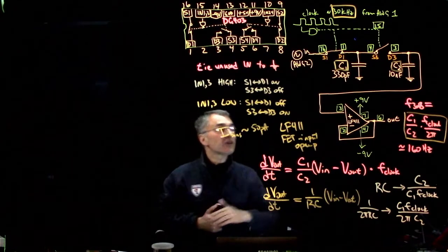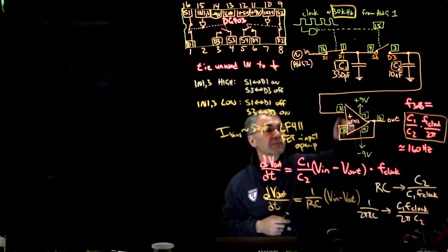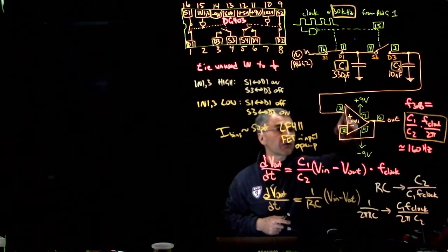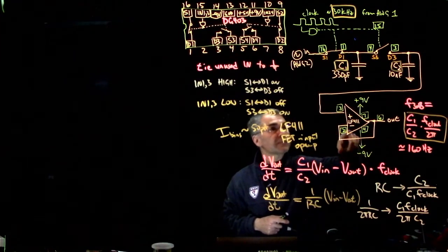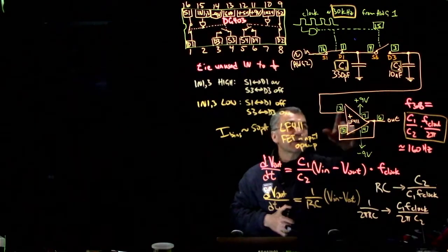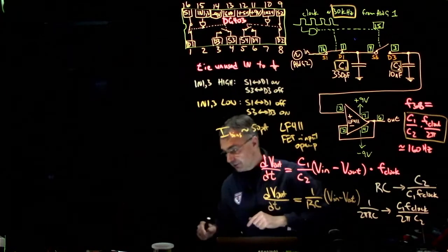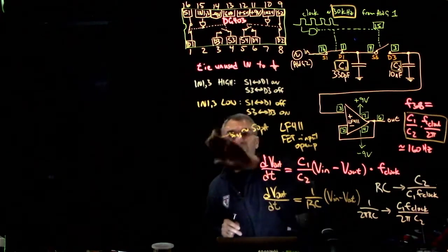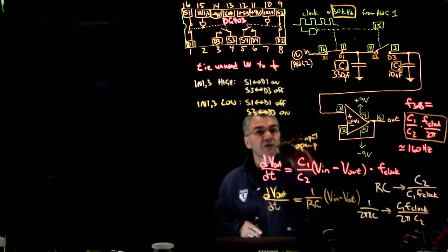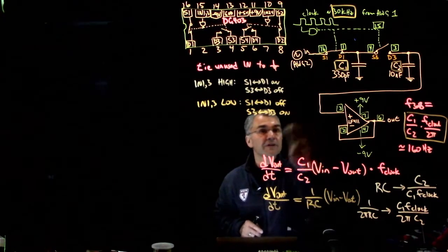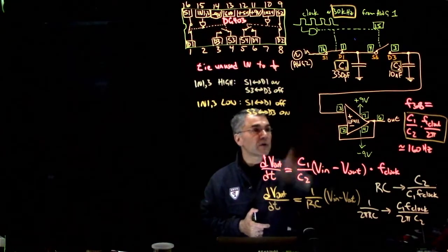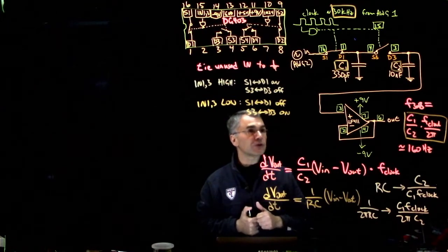So that means that when we connect this op amp follower, this is just a conventional follower, right? This 411 is wired up as a follower, and it is following this voltage signal. The advantage of following it with this FET input op amp is that this input really does draw almost zero current. The golden rules say that in op amps, inputs draw a negligible current. Well, with a FET input op amp, it really is truly negligible.